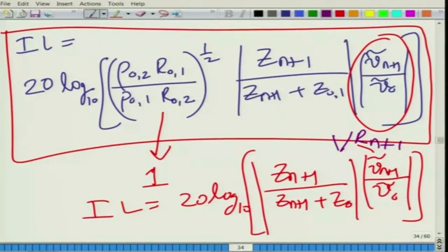So, for hotter gases sound speed is increased, and as the gases cool down towards the tailpipe, the temperature reduces, and so does the sound speed. It is directly proportional to square root of T. Of course, a lot of analysis assumes a constant sound speed. So, that is what we are going to do in this course, without complicating matters.